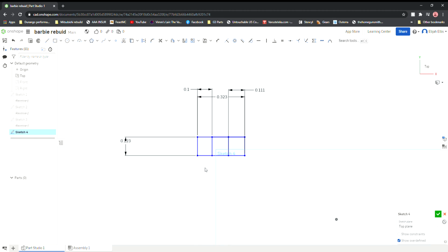Escape line. Which means I need to take this end piece and knock it down, which is 0.169 divided by 2. That's 0.85. Let's see, can I catch 0.85 just off this? 0.85. Select that across. Escape the line. We will trim these guys off so we have our component shape here.